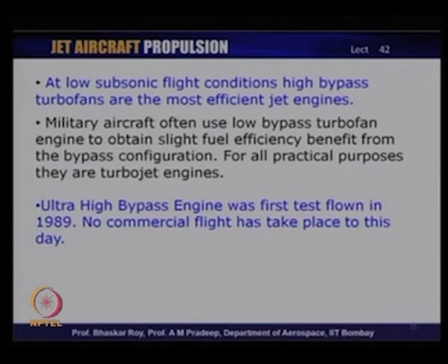However, military aircraft, which often fly under high subsonic to transonic and low supersonic speeds for various military operations, have started using low bypass turbofan engines. Even though for a long time they were using only turbojet engines, they now use low bypass turbofan engines, and that gives them a slight fuel advantage. The turbofan or the bypass always gives a slight fuel advantage over a pure turbojet, and this has been used by military aircraft engines up to Mach 2, giving them more operational flexibility, more range of operation, and more time in flight. These are the things that would be beneficial to military aircraft when using turbofan